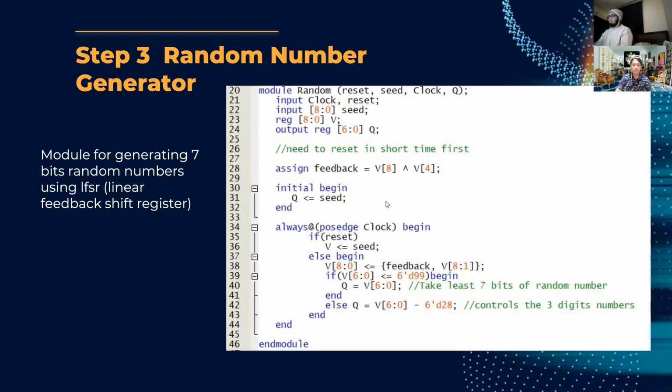Basically there is a stream of binary numbers, and it shifts the bits one way, in a linear fashion. As it shifts, the first bit that is left empty is treated as feedback, which is the binary product of the stored bits. We do this to make it as random as we can, so the generated number is called a pseudo random number.